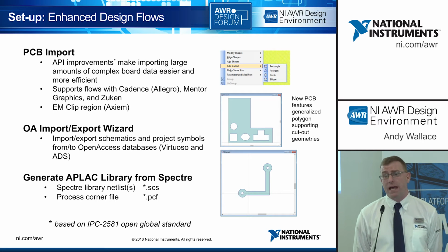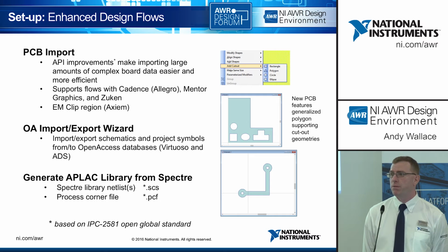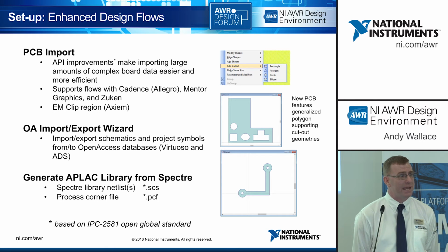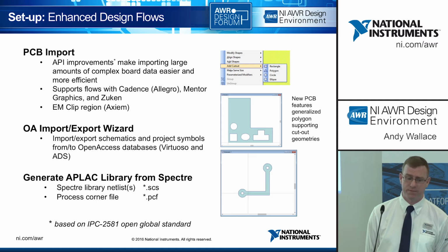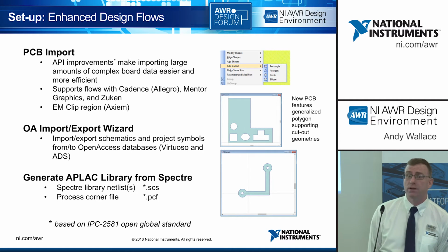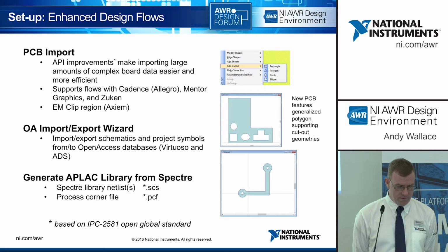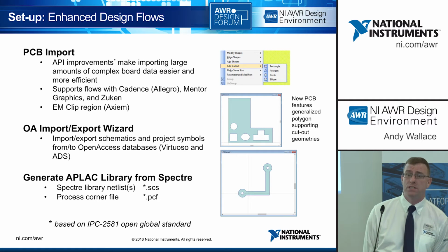So specifically on the setup, the PCB Import is a massive improvement in version 13. There are several standards out there. ODB++ is one I come across regularly. The only problem that we've found with that is it's an evolving standard and keeps changing. Software vendors like ourselves are constantly playing catch up to make sure that we stick to that ODB++ specification. So what we've chosen to do is follow the IPC 2581 global standard. It's a lot more fixed. That is a superset, if you like, of the ODB++ files, and it allows us, over either the advanced programming interface, to import board designs.